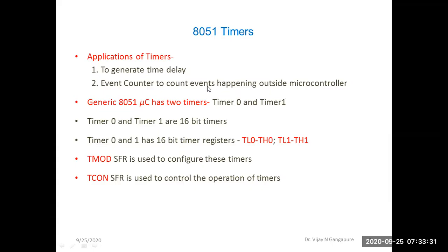So these pulses represent events that are happening outside the microcontroller, and we can employ timers of the 8051 to count these events, means to count these pulses. In that case, that timer we are using as a counter. So this is the second application of 8051 timers.